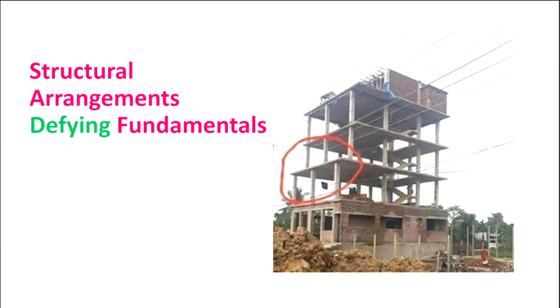Now here you can see, what is wrong here? Can any participant tell what went wrong here? It's not a railway building, but maybe some other building, just to have an insight into how planning can go wrong. Where is the problem? Column is resting on a slab, sir, which should not be the case. Either it should be on a column or supported by a beam. Very correct, but can you identify why he must have done this?